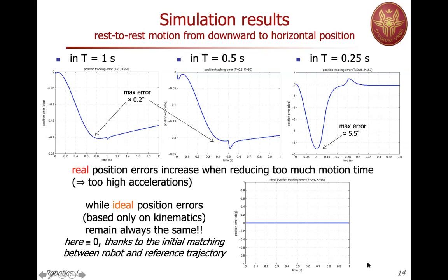You have to know, of course, the bounds, and then you can compute while you're getting data from your system, so from your robot, if you're violating or not, and if you're violating, you're increasing the K of violation until you have completed the motion, and only then you can check what is the most violating instant and value of K, and then you scale things. So you can do this without plotting anything, but in practice, you have to collect the data of all the motion before understanding which is the worst instant of violation, or if there's no violation at all.